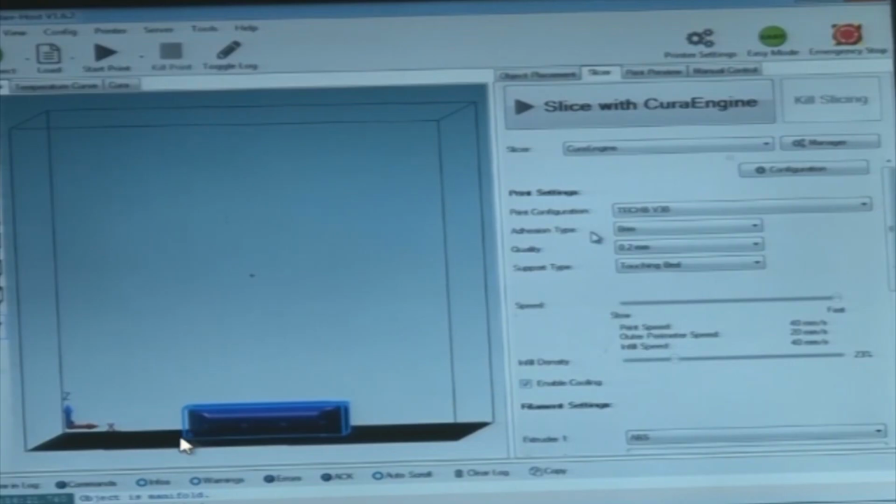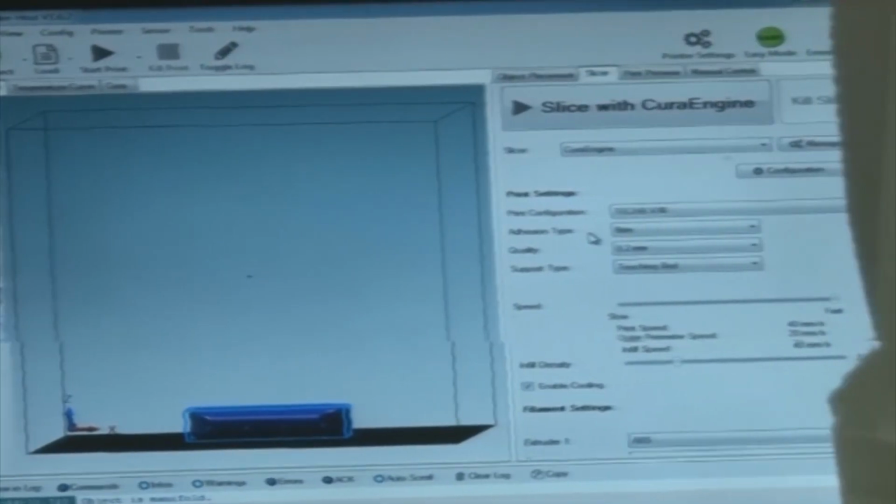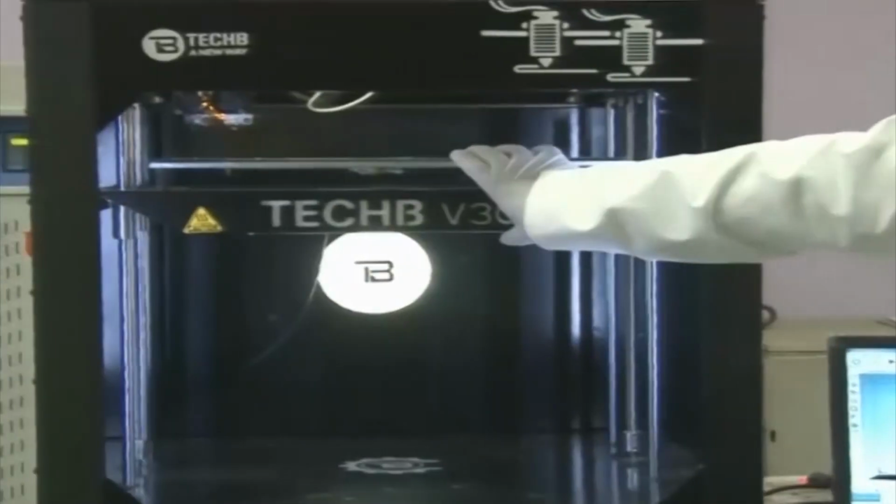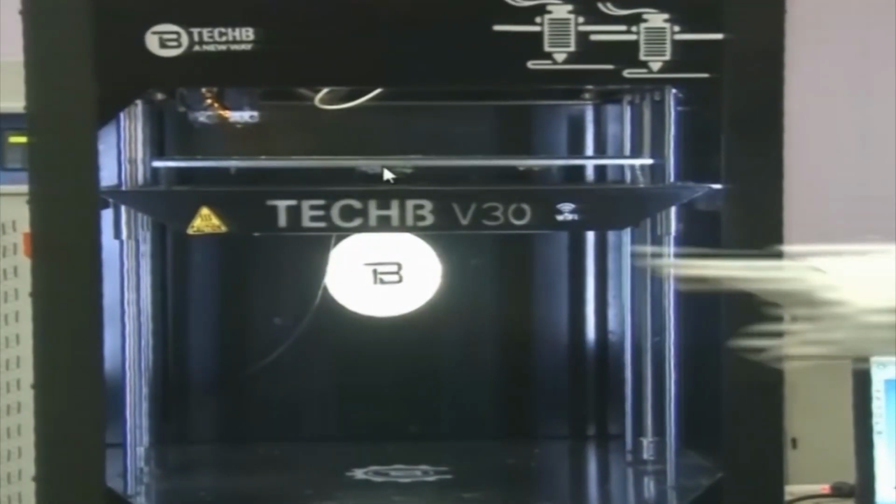Like this is the model, the skirts along this can be built. The skirt can be brim or raft. This plays a very important role, because this layer will stick with the machine, this tabletop, this hot plate.